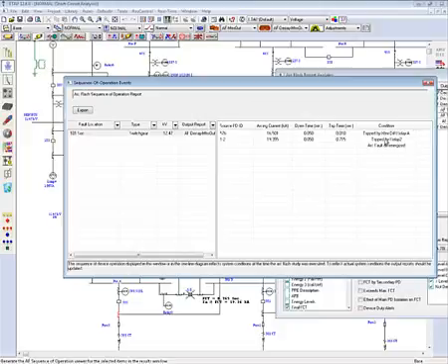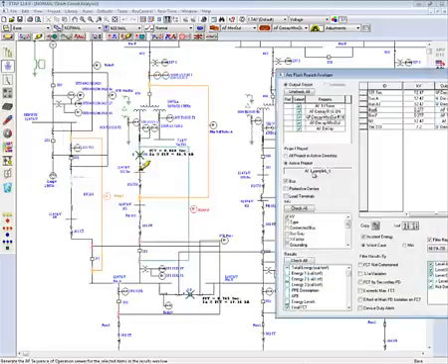And it is shown here that 576 is being tripped by differential relay A, and downstream relay 2 is operating circuit breaker 1-2. Now none of those being the relay 16. So now I know that there's something wrong or something has been configured with my relay 16 incorrectly.